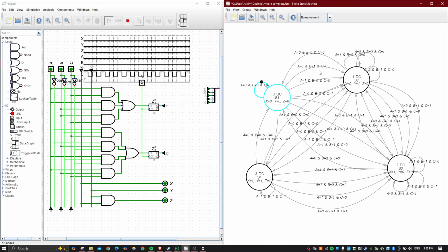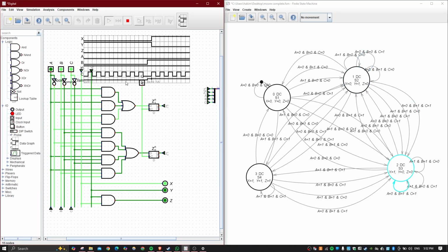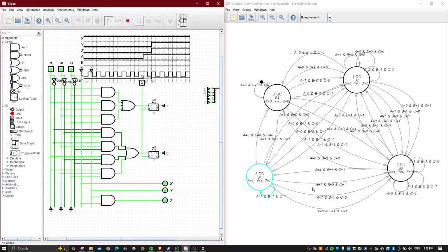If one sensor detects a dangerous level, it goes to state 2. If two sensors detect a dangerous level, it goes to state 3, the dangerous state. And lastly, if all of the sensors detect a dangerous level, it will activate the monitor to show that it is a deadly level, and the buzzer will be activated.